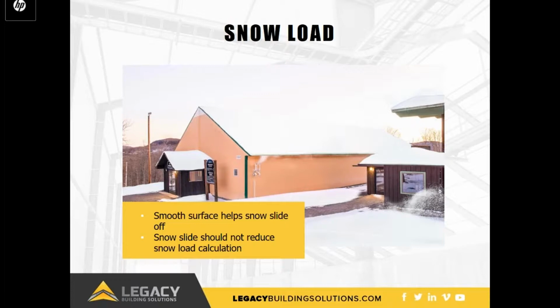In many parts of the world, snow places significant pressure on the building roof. Any reputable building manufacturer will calculate the roof snow load. The building's ability to withstand snow depends on the shape and angle of the roof, the building's exposure, thermal factors, obstructions on the roof such as vents, and of course the roof cladding. Fabric has a smooth surface which makes the snow slide off it more quickly.